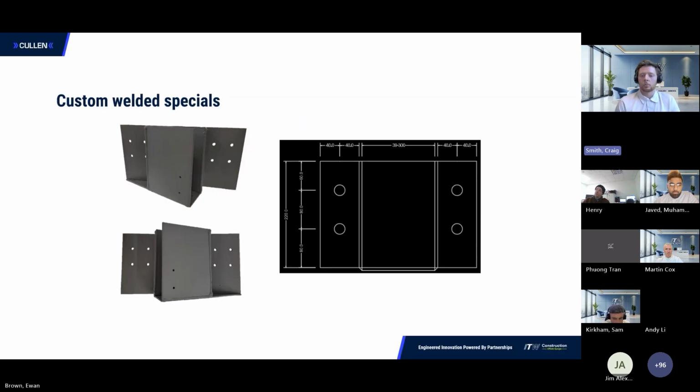And then just very quickly, we also do custom welded hangers. These are for projects beyond the standard range that we've talked about, and they're different from our standard welded hangers as well. They're tailored for specific angles, skewed or sloped, and also higher load capacities. They're made to order. We can adjust the steel thickness and the geometry of them, and various fixings can be used like PSTS screws or bolts to further increase the load. This all depends on the strength of the header as well. They're ideal for complex or high-spec projects.